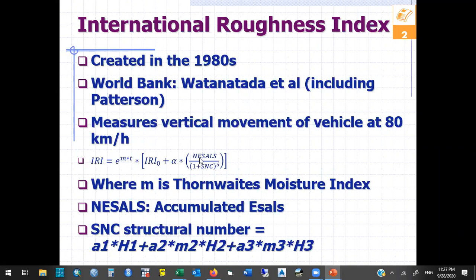You can always use the core of the equation where you have the number of load applications. So this is load cycles, the same we have been seeing before, 1,000, 11 million. And the structural number, which is the strength of the layer, which we covered before. So you divide those two, this to the power of 5. You have a coefficient here that is a calibration constant.